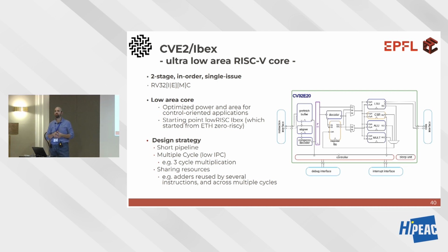Then, as we said yesterday, adding the C extension will make the CPU bigger, right? Because I have to decode more instructions. So shall I add it or not? Depends on the memory footprint. Yeah, exactly. Thanks a lot. So the answer of your colleague was: it depends. Actually it's better to compress the code, because if your code is big and you save 30%, you save SRAM area. So yes, I had the compressed extension.